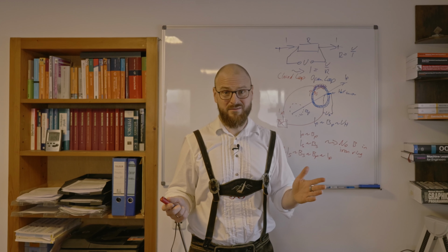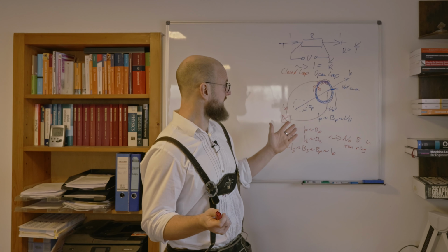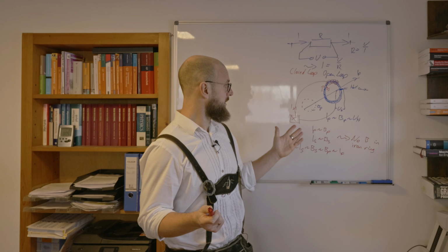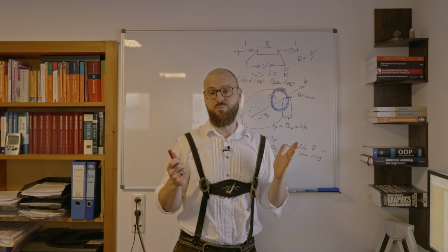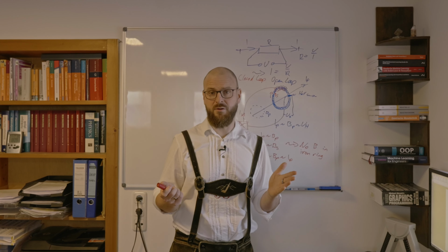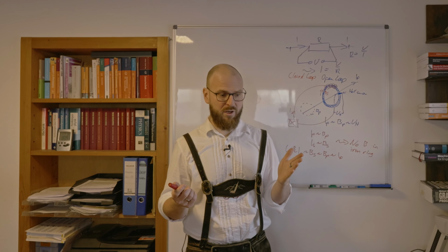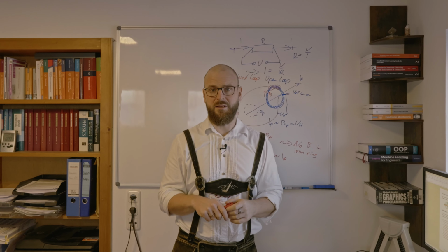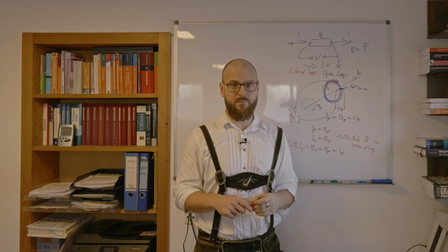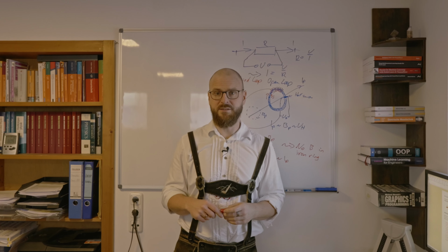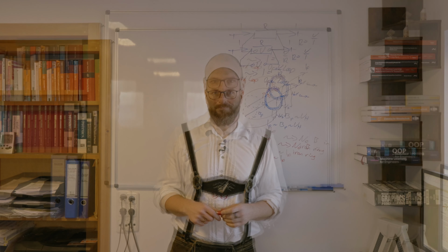And by that, they're usable, quite flexible, simple, and are very often used for measuring as part of a power measuring unit. So a power measuring unit bringing along some wires for measuring the voltage, and such a closed loop magnetic current measuring system for measuring the current.